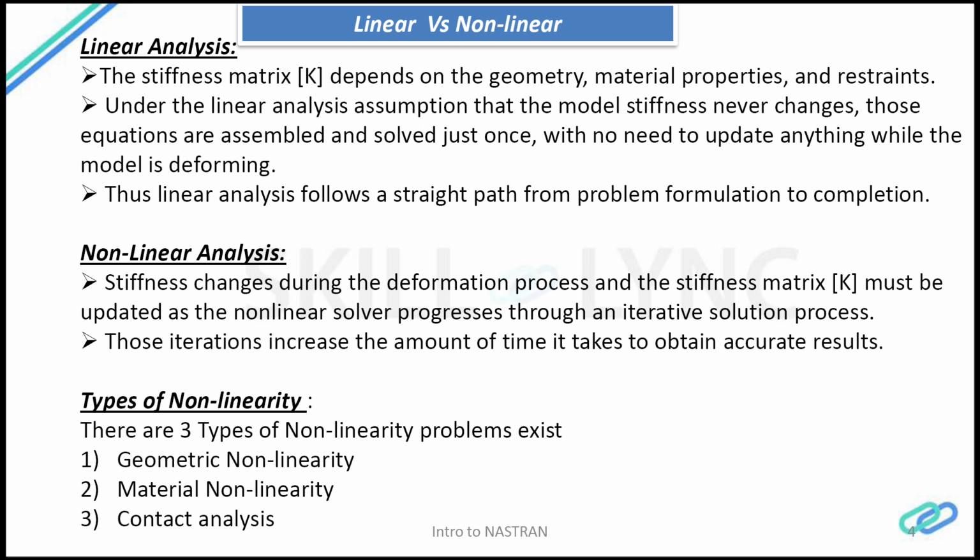The reason behind it is that there will be a change in the equilibrium of the structure. So the behavior of the structure, whether it's a large deformation or whether it's a plastic region, whether the material goes from elastic to plastic, and those kinds of reasons, the stiffness matrix needs to be updated, and it's an iterative process.